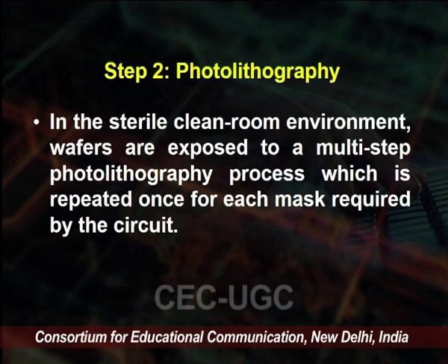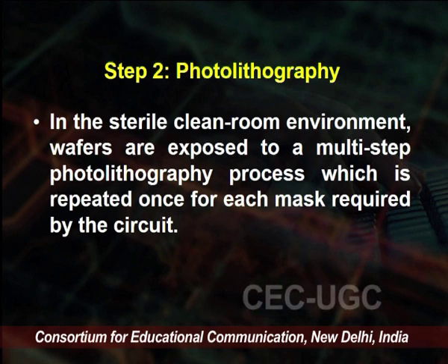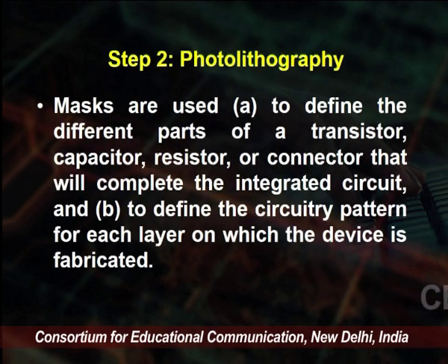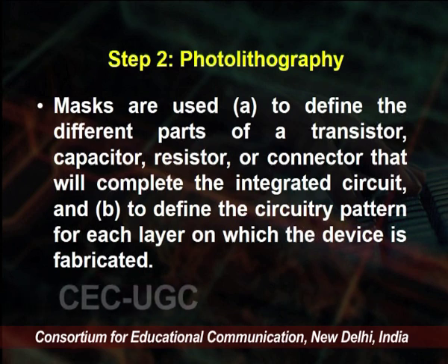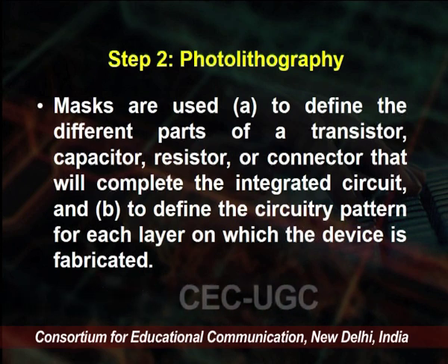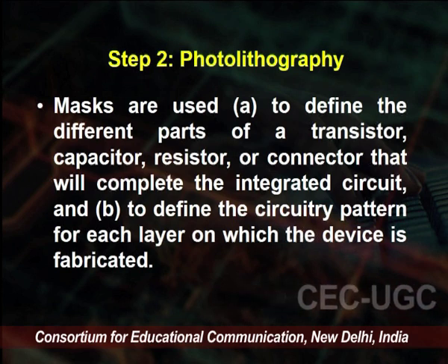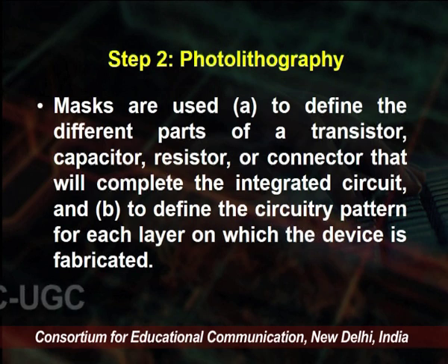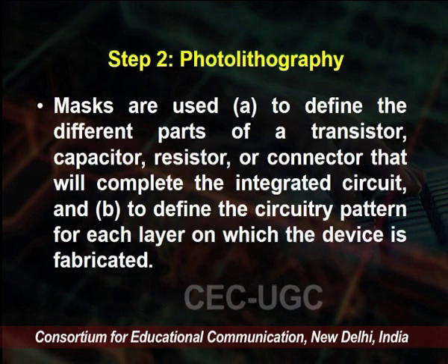This method is used for all the different devices. Masks are used to define the different parts of the transistors, capacitors, resistors or connectors that will complete the integrated circuit, and define the circuitry pattern for each layer on which the device is fabricated.